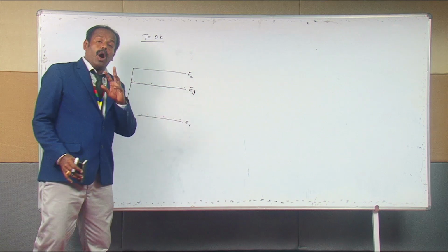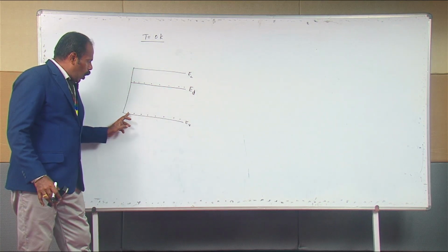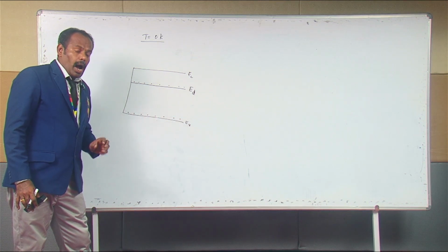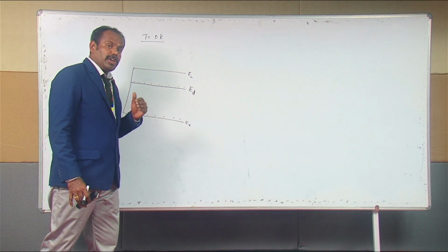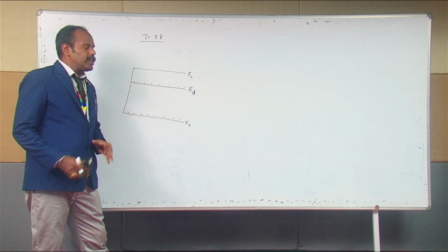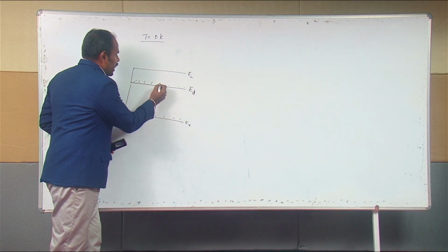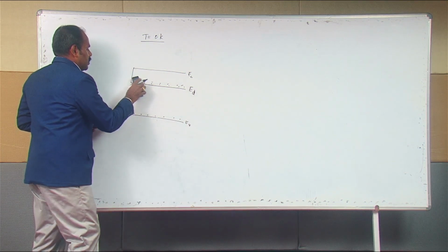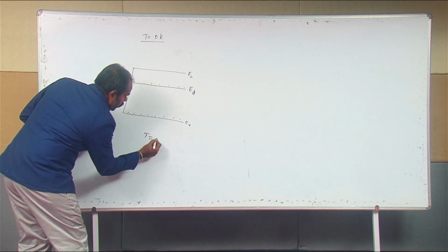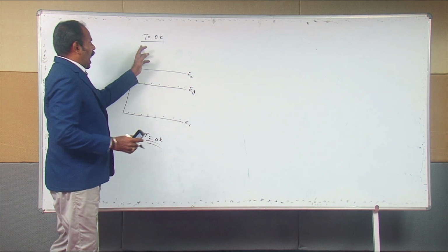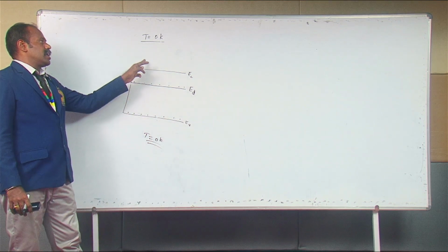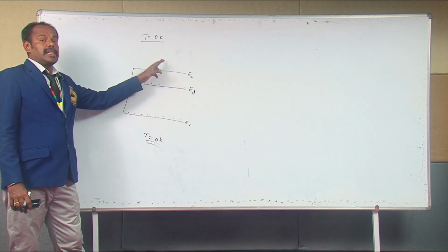Okay. So all those electrons which are involved in the covalent bond formation are present in the valence band, and all those free electrons which are newly introduced into the system because of the addition of the pentavalent impurity atom will all be lying in the donor energy level. Okay. So this is the structure of the energy level diagram at T equal to 0 Kelvin for an N-type semiconductor. And you can clearly see that there is no presence of free electrons in the conduction band.